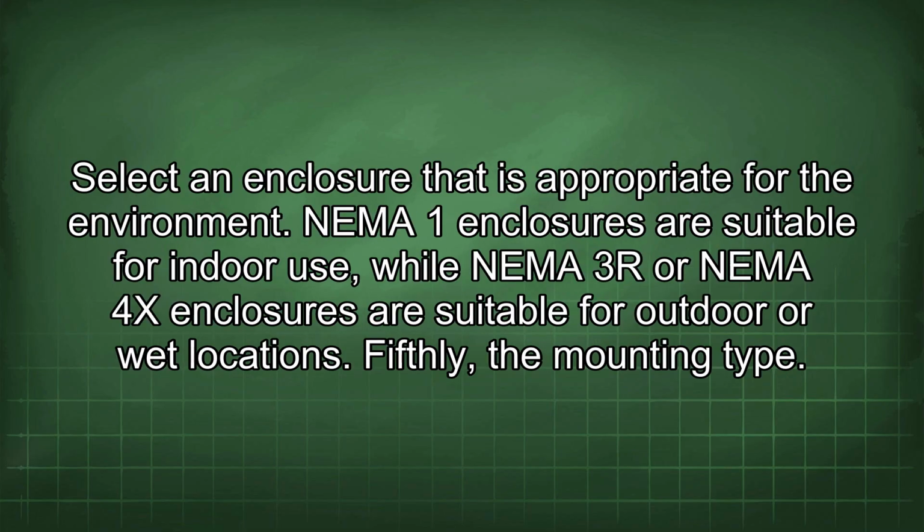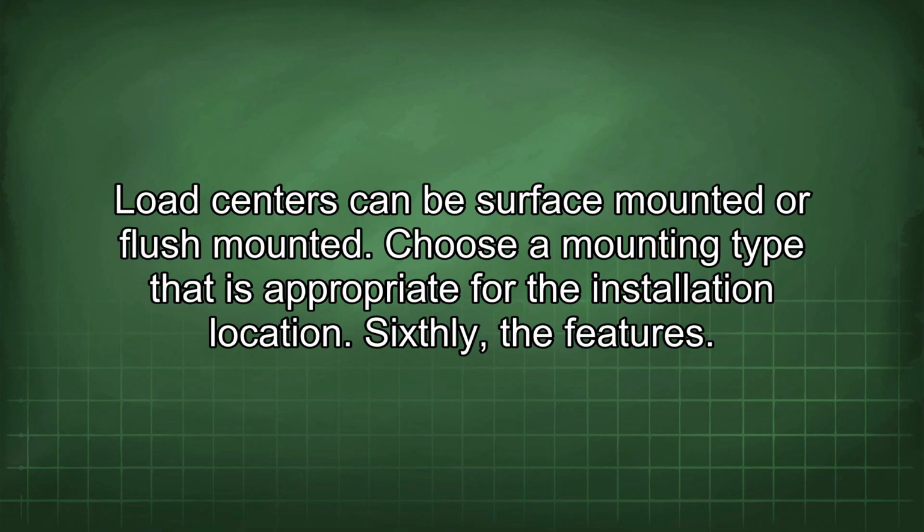Select an enclosure that is appropriate for the environment. NEMA 1 enclosures are suitable for indoor use, while NEMA 3R or NEMA 4X enclosures are suitable for outdoor or wet locations. Fifthly, the mounting type. Load centers can be surface mounted or flush mounted. Choose a mounting type that is appropriate for the installation location.